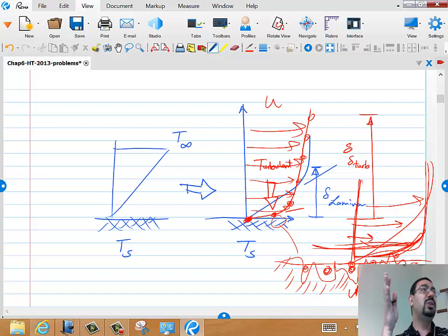And if you take 4273 experimental fluid mechanics, you would hear more about how to come up with that velocity profile. Actually, we solve for that velocity profile, and you know exactly how much friction this thing generates and how you can use the shear stress, right? So there's a whole course to study this fluid mechanics motion. But the point I'd like to take from here is that there is a velocity profile, all right? And that velocity profile depends on the viscosity of the fluid, how sticky it is, or basically on the mu. What's mu? That's the viscosity of the fluid, all right?